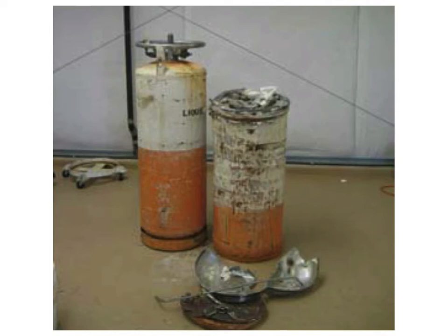The cylinder had been standing at one end of a 20-foot by 40-foot laboratory on the second floor of the chemistry building. It was on a tile-covered 4 to 6 inch thick concrete floor directly over a reinforced concrete beam. The explosion blew all of the tile off the floor for a 5-foot radius around the tank, turning the tile into quarter-sized pieces of shrapnel that embedded themselves in the walls and doors of the lab. The blast cracked the floor, but due to the presence of the supporting beam which shattered, the floor held. Since the floor held, the force of the explosion was directed upward and propelled the cylinder, without the bottom, through the concrete ceiling of the lab into the mechanical room above.